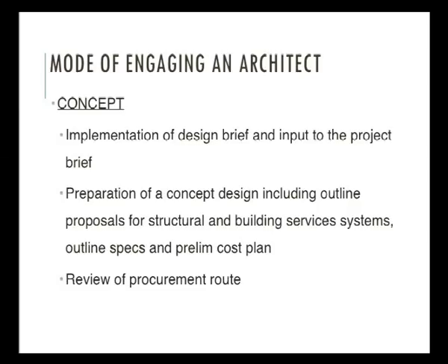There we go, start with the concept stage: implementation of the design brief and input to the project brief. This has a direct link to the concept, yes, the client's need again. Preparation of a concept design, including outline proposals for the structural and building service systems, outline specs and prelims, cost plans, review of the procurement route. And students, this is why your staff always want you to have a conceptual plan before getting into AutoCAD or drafting straight away. So keep the habit of conceptual scheming first.